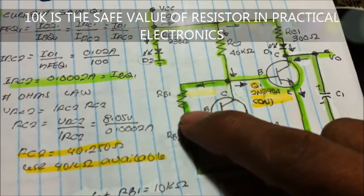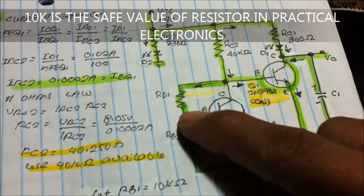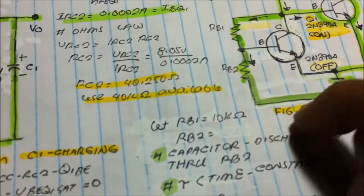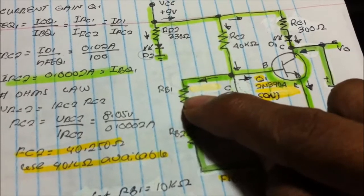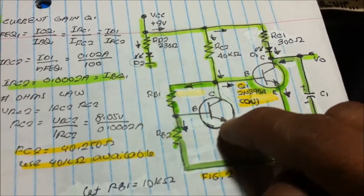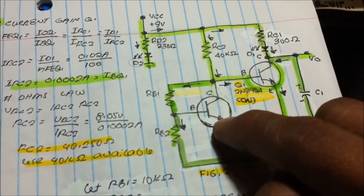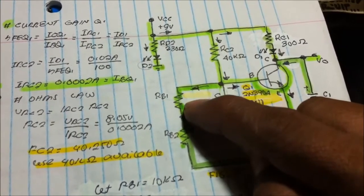Usually in practical electronics, we are using an arbitrary value, which is 10 kilo ohms. That is the safe value of the RB1, the safe value for biasing this type of transistor configuration, a base bias configuration or fixed bias configuration.